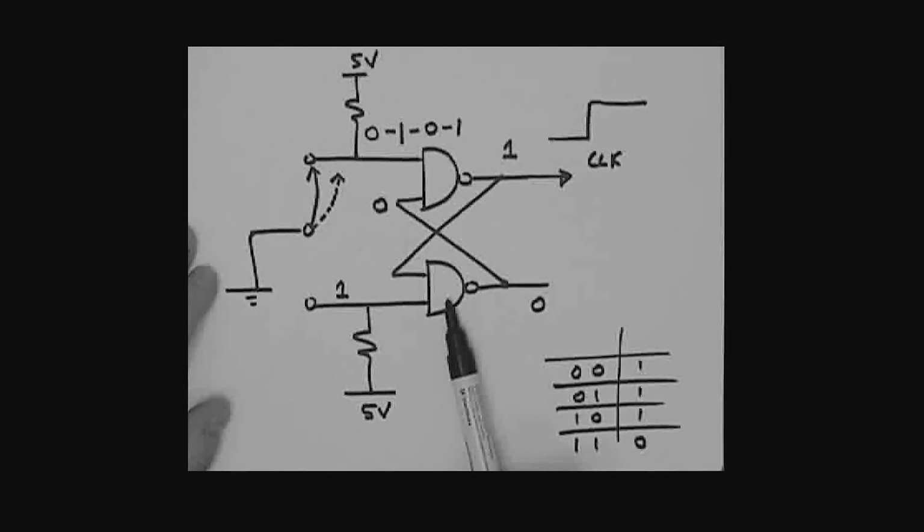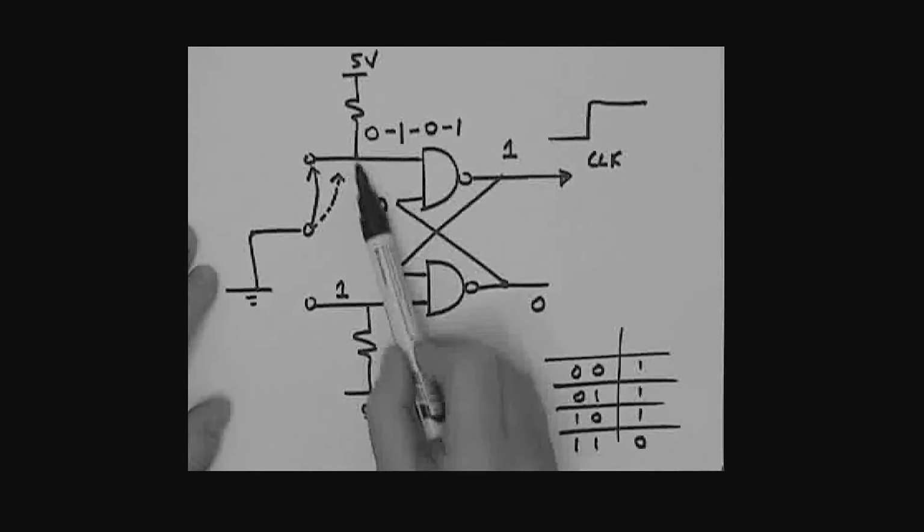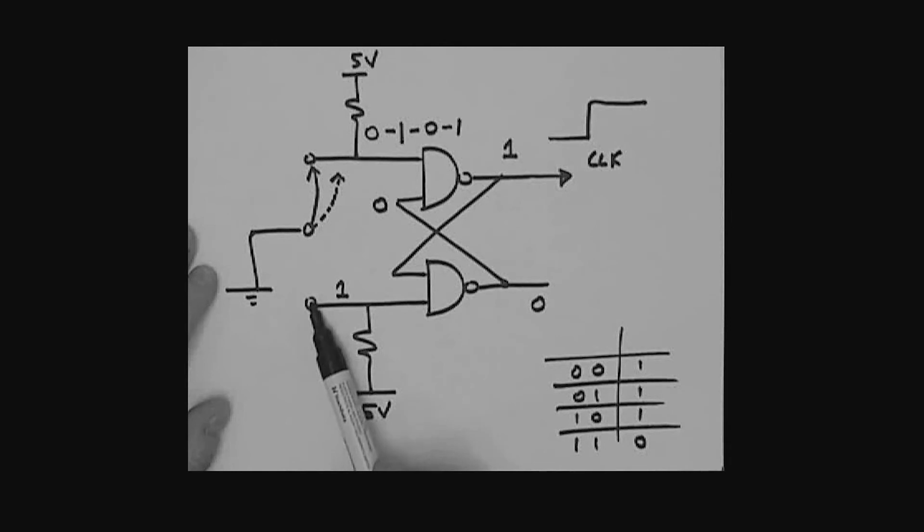So what have you got? You've got basically two NAND gates configured like I'm showing you here. You've got these inputs connected through a resistor to 5 volts on either side. And remember, this is your switch over here, a single pole double throw switch. Now your only challenge is to find out where the common terminal on the switch is, and you can do that with a DVM. Now look, that's going to basically end this particular video.